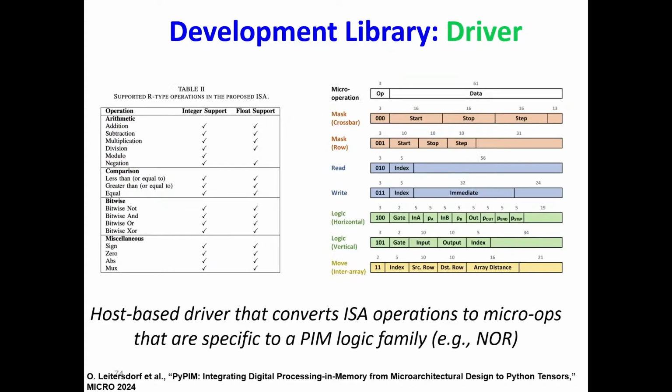And the driver is the ingredient whose role is to move from the architecture to the microarchitecture. So it's tailored specifically, in this case, to the mMPU. The idea is to take the instruction from the instruction set architecture and map it into the micro instructions of the microarchitecture. For example, if we want to do a division, then it becomes a set of NOR operations, and we relied on arithmetic as the basic development for arithmetic operations.